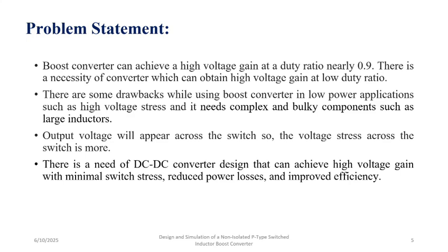Coming to the problem statement, a boost converter can achieve a high voltage gain at a duty ratio nearly equal to 0.9. There are some drawbacks while using a boost converter. Output voltage will appear across the switch, so the voltage stress across the switch is more. There is a need for a DC-DC converter design that can achieve high voltage gain with minimal switch stress, reduced power losses, and improved efficiency.